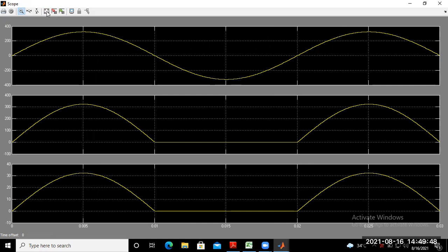Okay. So this is your sinusoidal input voltage. You observe this one, and this one is your phase delay. If you consider 0, okay, then your output voltage will be something like this one for the positive half cycle. This one is reverse bias from this point to this point, pi to 2 pi. So you will get the output voltage as 0. So this one starts conducting when the gate pulse is given, that means at 0 degree.